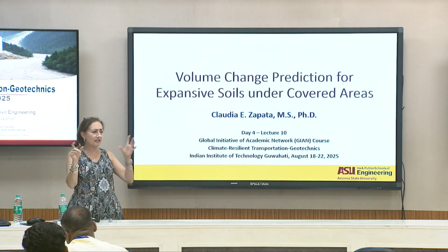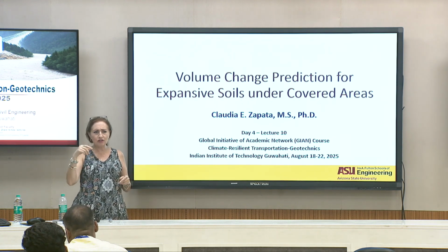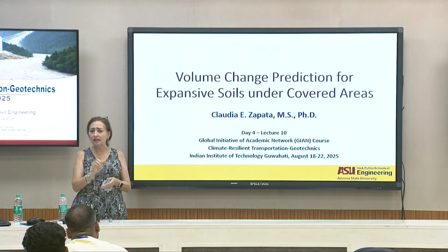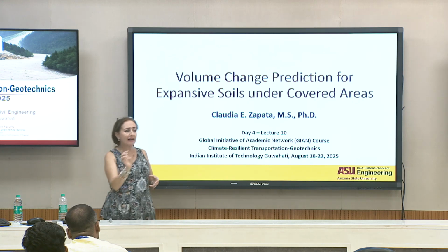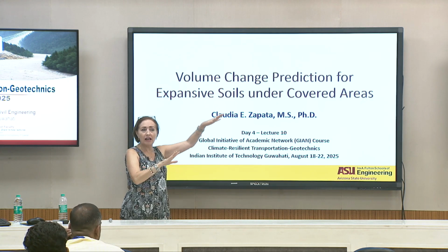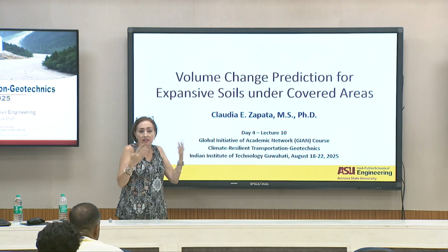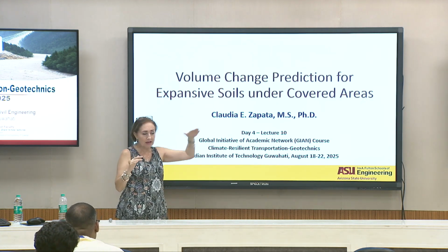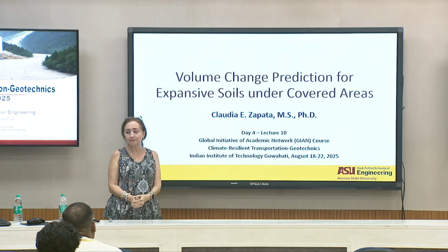You get PI passing 200, infiltration or rainfall or something, and then you add some roughness to the road due to that, and you design for that roughness value, and that's how you do it.